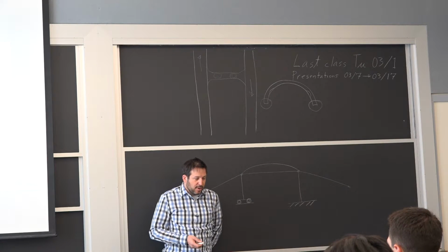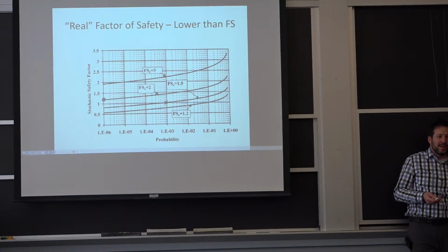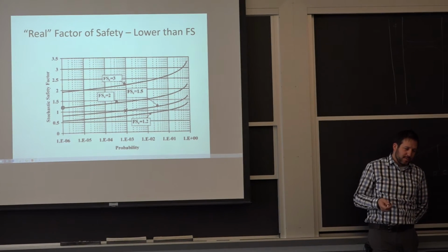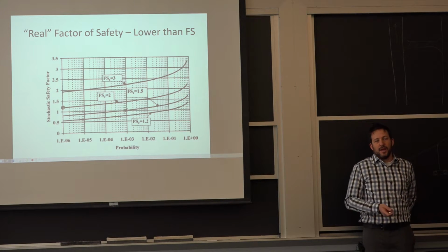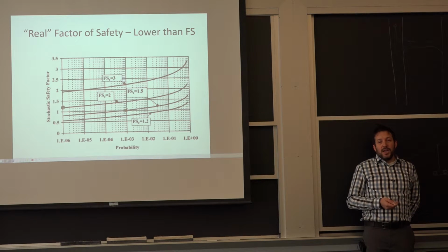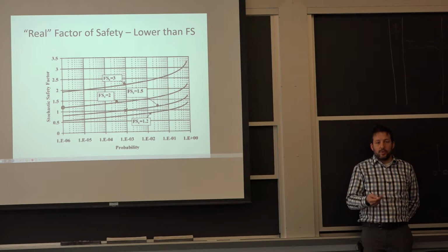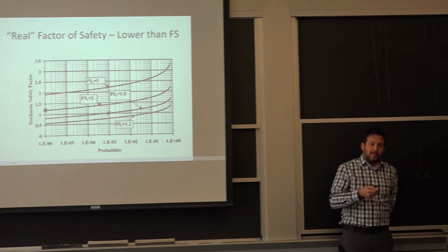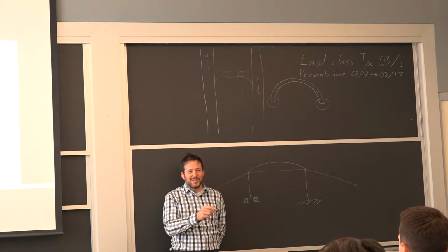So it does come into my practice right now with pipelines. So pipelines, if they're in the ground on average for 30 or 40 years, of course they had some corrosion. Of course, they've been through some cycle of loading, and there's going to be some fatigue cracks in them. And therefore, the way people used to think of them for design and strength purposes when they were new doesn't apply anymore. So the same way for an old bridge like this, okay, well, was it built to code back then? And in that case, no. So that's already a problem.